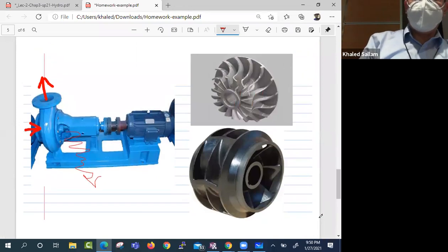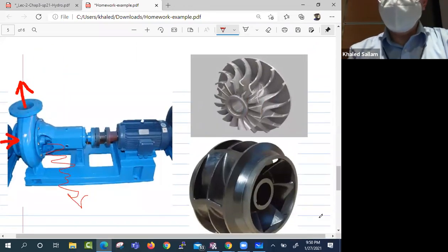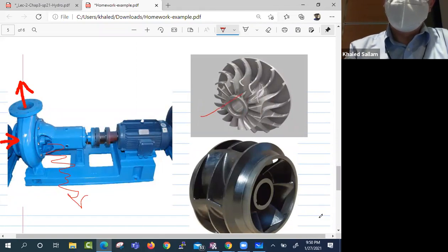And for an air compressor, by the way, it looks the same, huh? Except that because it's rotating at very high velocity, V1, of course, will become like this, but because of the U, W would be this way. How did I tell that W is this way? Because of that plate.